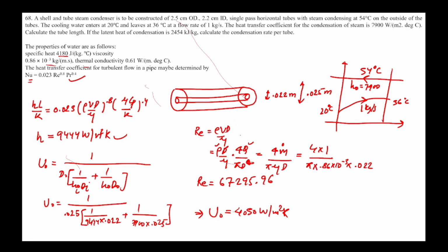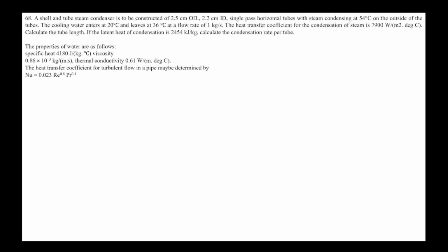So applying energy balance, heat gained by cold fluid is equal to U A theta m, that is U pi d L theta m.